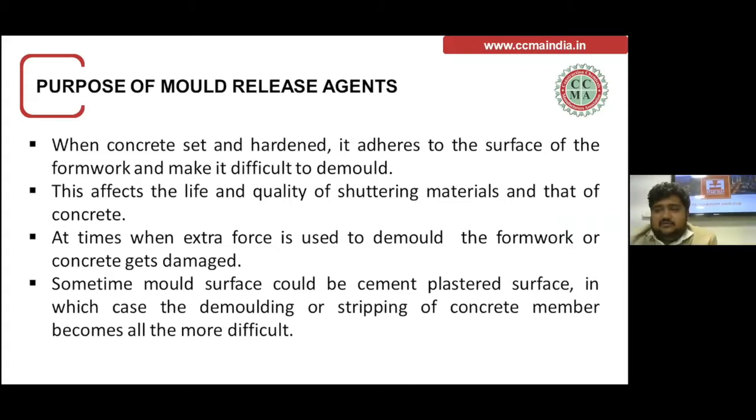I think everyone who is here has seen it happen once in their life at some site or somewhere. But it is there, and this problem is quite big in the industry. Sometimes the demolding could be of a cement plastered surface, in which case the demolding or stripping of the concrete member becomes all the more difficult. So this is the reason why we need a good demolding agent.